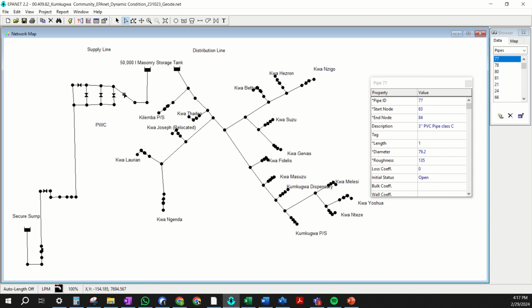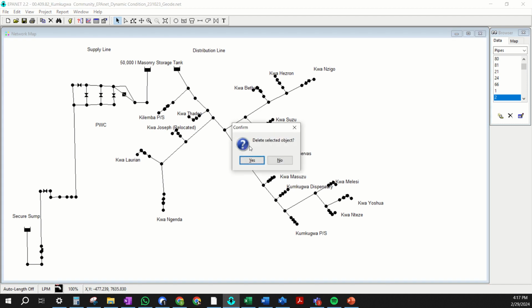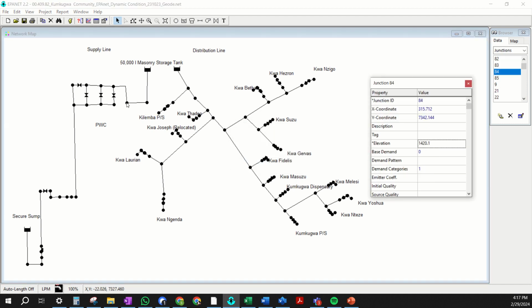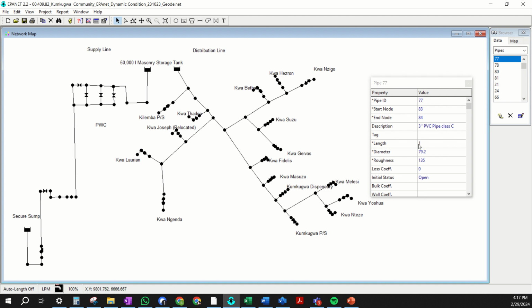I'll add a vertex here to make it look nice and neat. Looks like there were 2 pipes, so I deleted one. So this should be 1.5 meters, or really it goes over and down, but then it continues and goes out of the treatment house, so it will be longer. And this pipe can actually represent all the additional length of pipe that's inside the treatment house before and after the chlorinators. You can use one pipe to model all of that, just to keep your model more simple rather than having a pipe before and a pipe after.